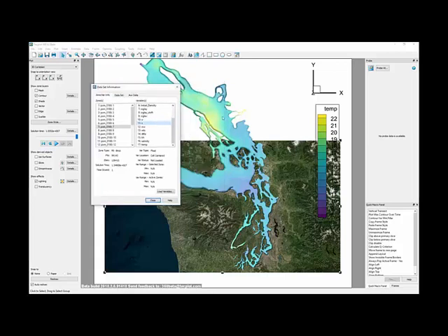So in this case, we're showing X, Y, Z variables, and we're showing temperature. So as we go through this list, we can see that the variables that are not required are not loaded, such as latitude has not been loaded, initial density not loaded. So this is a way of Tecplot saving memory as you're loading your data. So you really don't have to be concerned about loading very large data sets. I have a 250 gig data set of Boston Bay, a simulation out in Boston, and I'm able to load it on my machine because of that memory management.